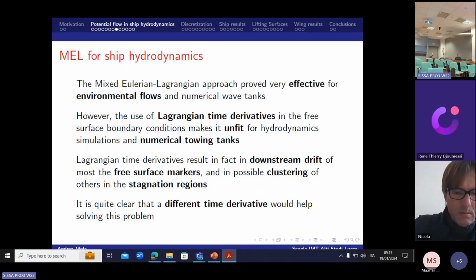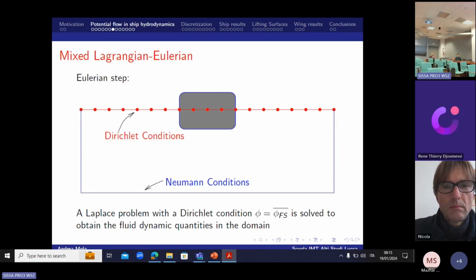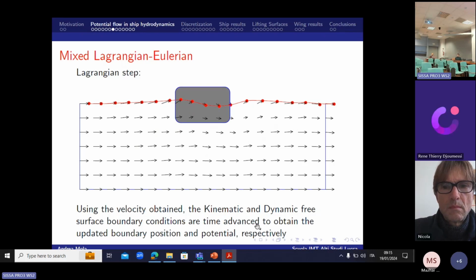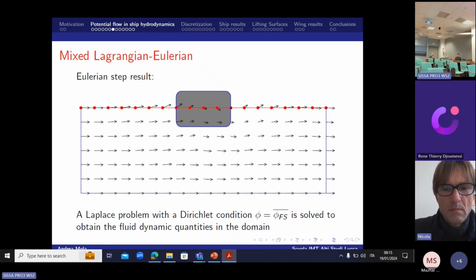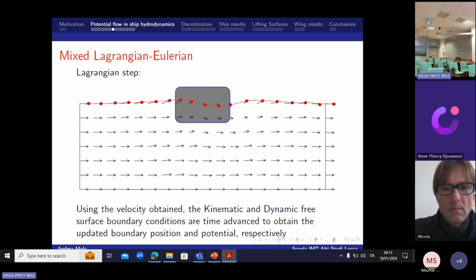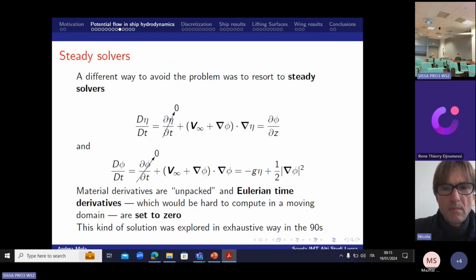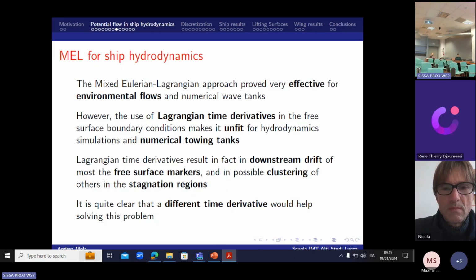The problem is that in the frame of reference of the boat, where you have an average stream, this runs into a bunch of problems. You can see already over here that after the first time step, my blanket, the red part, has moved downstream, and after a bunch of time steps, it will abandon the region where I actually want to solve my equations. So this model is kind of unfit to carry out steady and unsteady flow simulations for ship hulls that move in the water. It is instead very good to understand how a wave moves in a closed basin.